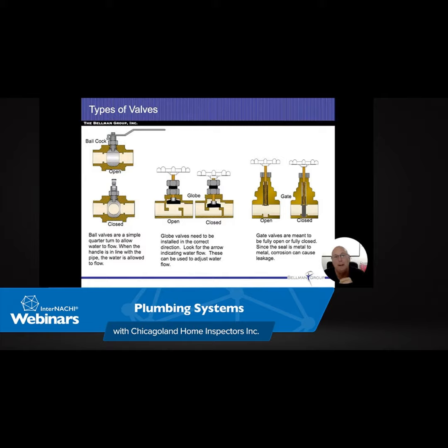So in this case, they're going to use what's called a baffle, or a barometric damper at the very top. Kind of looks like the old Napster logo if you think about it. That's actually on a hinge, and that's going to open. The hotter the air is, the faster the air is going to move. The faster the air moves, the lower the pressure will be inside that pipe.